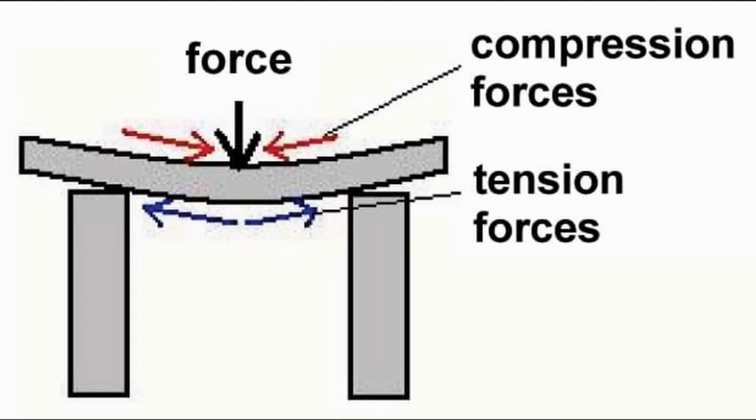Because nothing supports the bridge in the middle, the simple beam bridges are only good for relatively short lengths, because you don't want to put a bunch of load in the middle and then have your bridge sag with nothing to support it. So a way to get around this issue is that we can build a special kind of beam bridge, which is called a truss bridge.